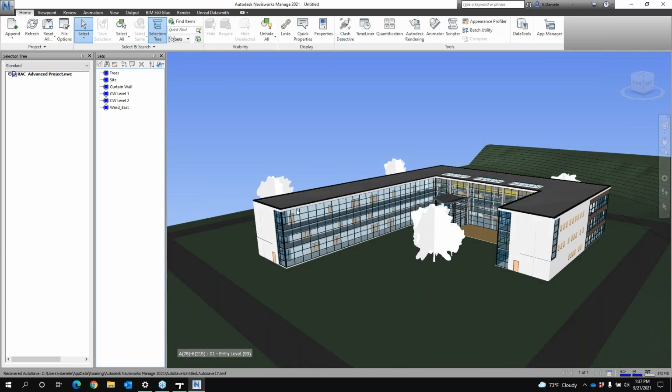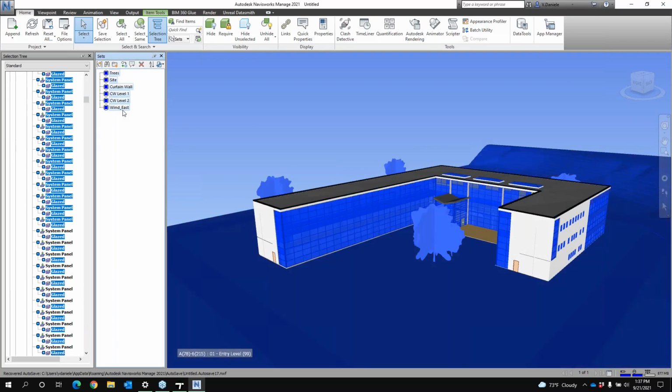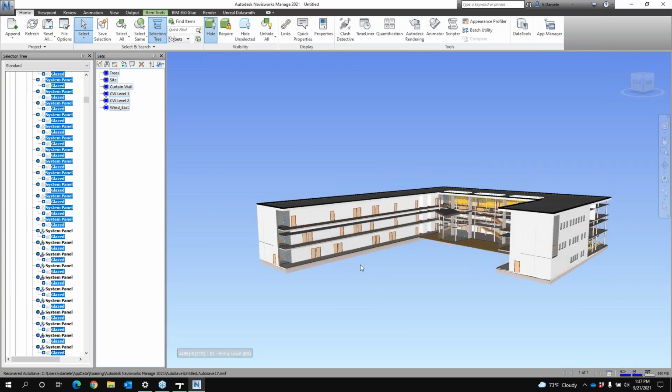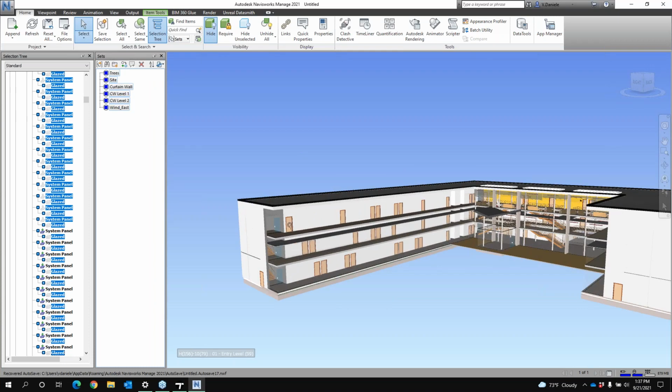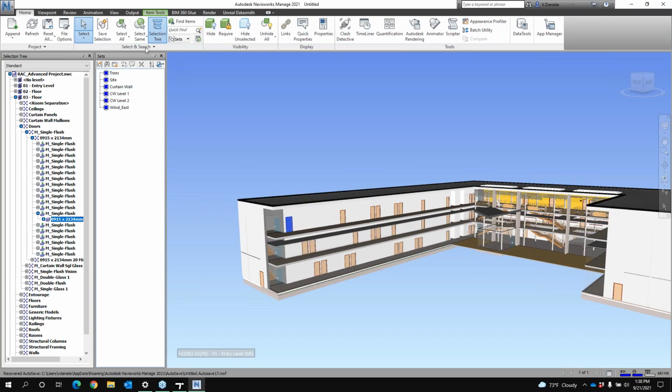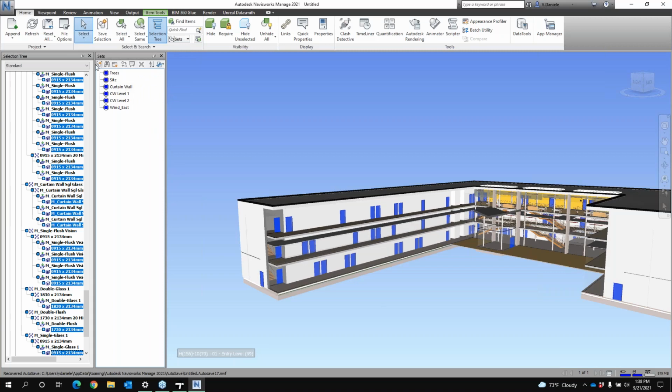So anyway, if we wanted to add something later on, or if we get to a point where you're trying to update the file, I'm going to hide the selection. Say we're doing something where we want to isolate our doors and remove them from our main model, so make them a new selection set. What I would simply do here is select all the same type of doors, create a new selection set for the doors,